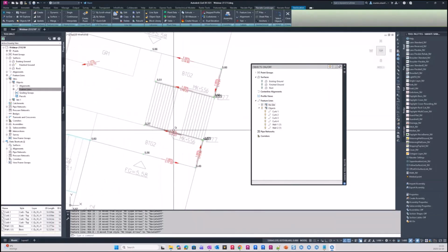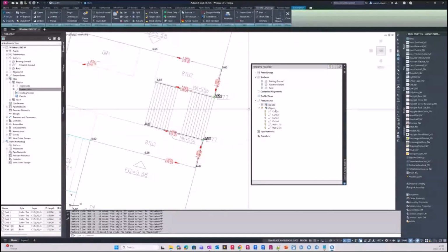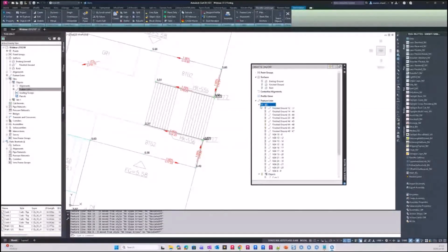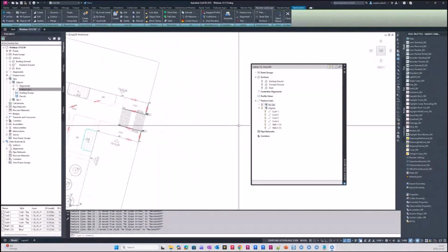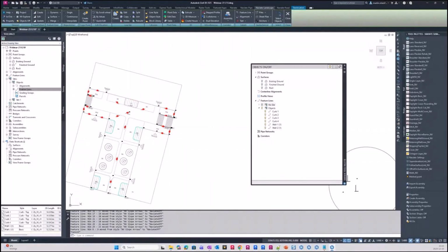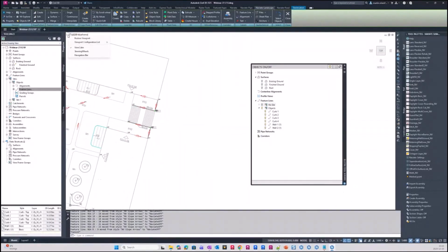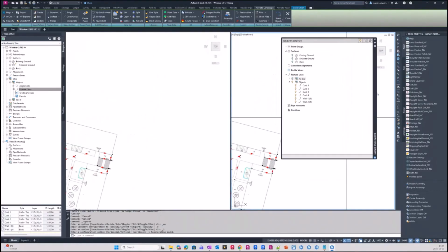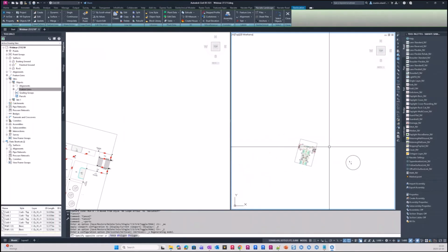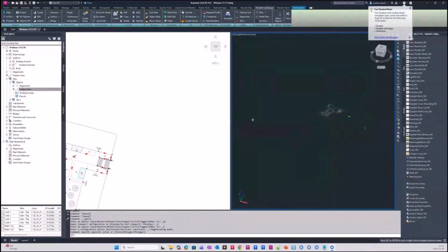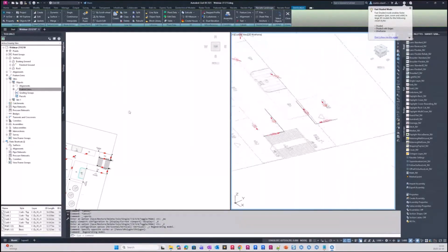So if you also want to use feature lines that should be visible, you can create another site to easily turn on and off those feature lines. Here's a tip. So I will switch here. So I got two viewports, and we will put one in 3D and one in 2D, so we can see what's happening in 3D as we do our 3D modeling.